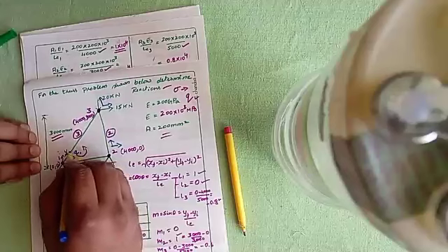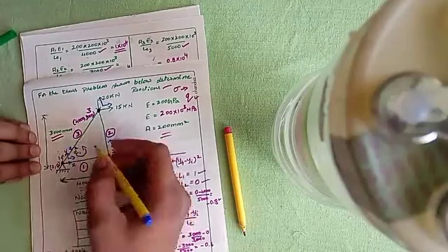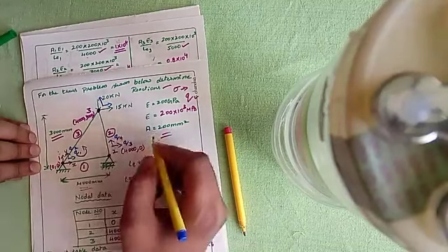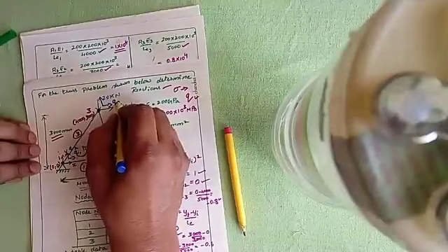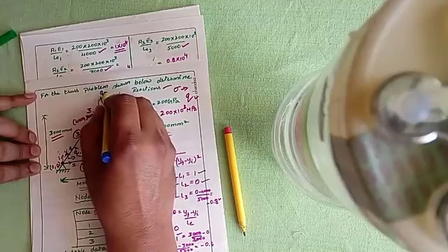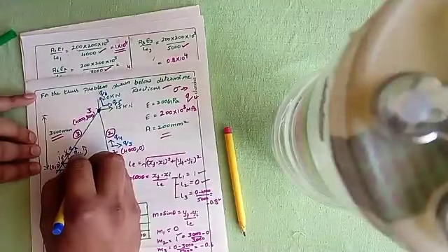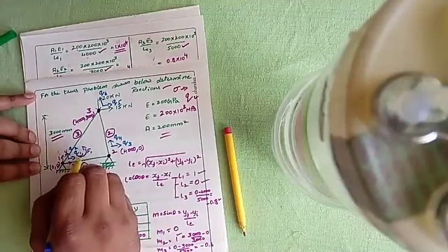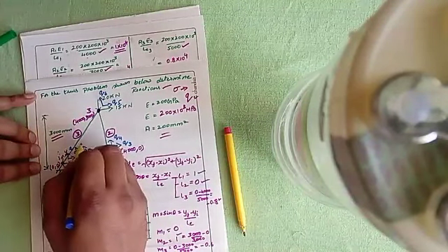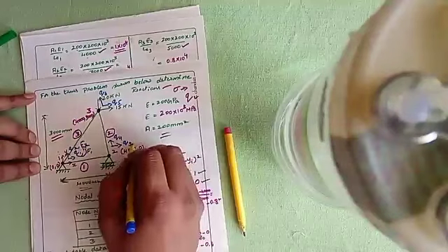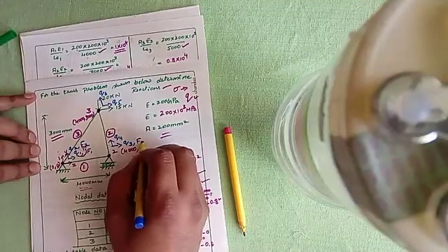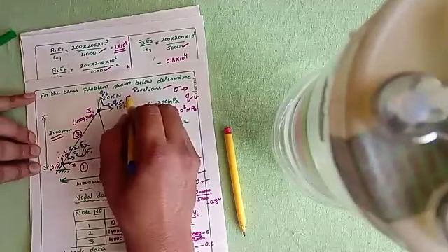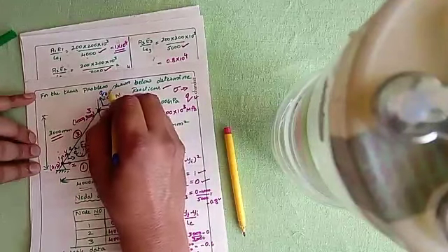So this is your q1. If you move in this y direction, q2. If you move in this x direction, q3. If you move in this direction, q4. And along the x direction, q5. And along the y direction it is q6. Meanwhile, I'll represent the force. The displacement occurred at q1, the responsible force is F1, and the responsible force for q2 is F2. For the displacement q3, the responsible force is F3, for q4 it is F4, for q5 it is F5, and for q6 it is F6.